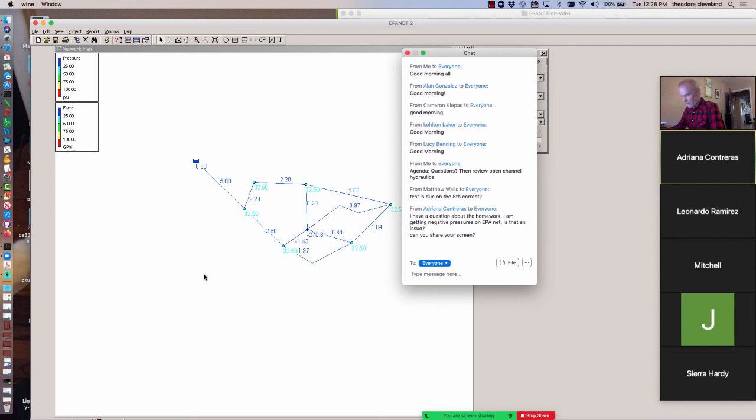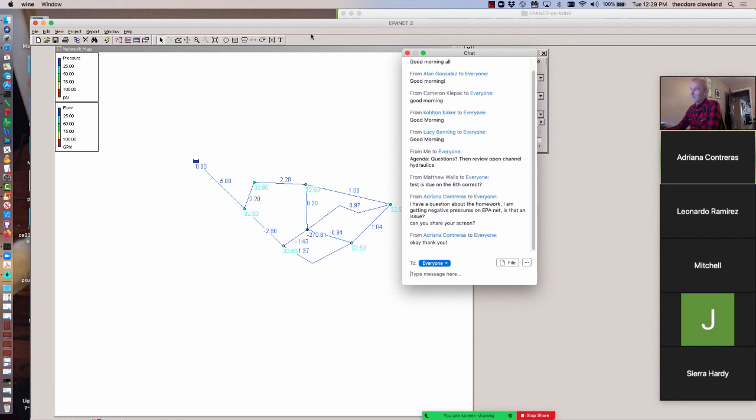The second one where you do the somewhere USA, your initial supply is 135 psi. If it turns out that that's not enough, go ahead and artificially jack up the pressure to get stuff to flow through the system so that you can verify that your other elevations are correct. And then we'll go back in subsequent work to figure out how to add a booster pump into that. So Adrian, does that confuse you even more or give you some guidance? So I'll go give you more guidance.